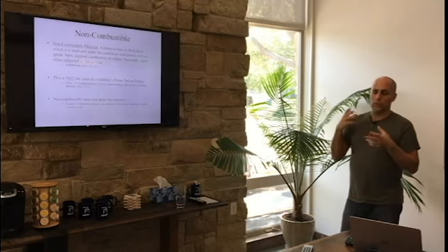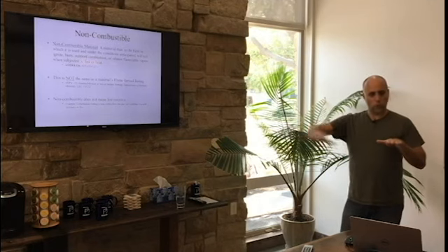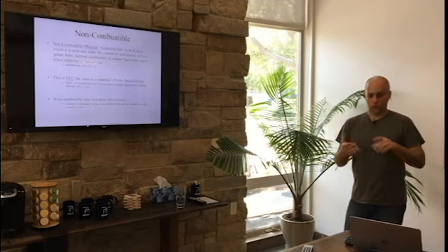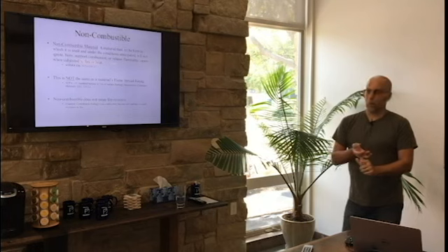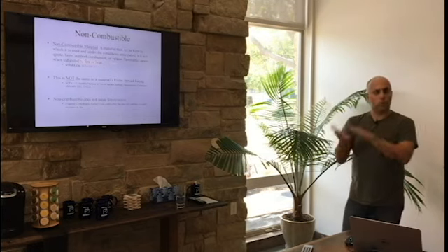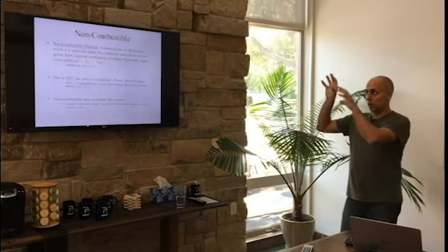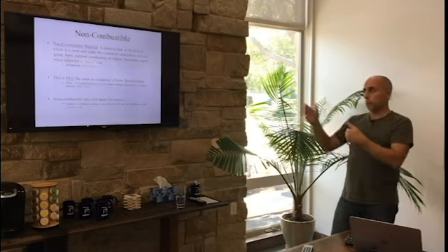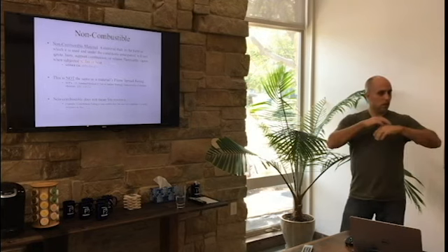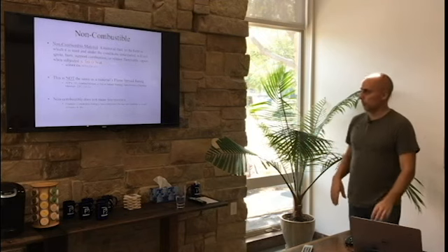The other one is material, you hear what's called a flame spread rating. That is, how will it burn across a surface? Flame spread only has to deal with surface materials. So you're talking flame spread of wall materials or curtains or any of those kind of things. There's different testing depending upon whether they're loose hanging or they're on a wall or on a floor. But flame spread is a totally different thing than whether it burns or not. Flame spread is how much will it burn across the surface. Non-combustible, doesn't burn. None of that means that it's fire resistant whatsoever. Okay.